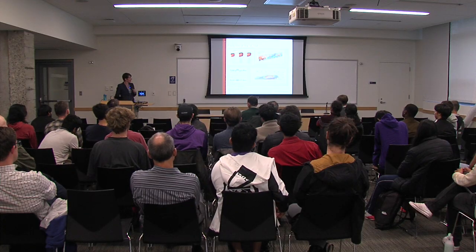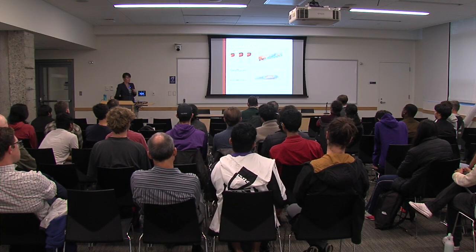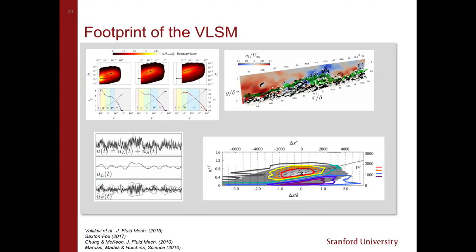So you would say that's a nonlinear effect. There are large scales here that are having an effect on the small scales. Good. You might even say close to the wall that if a large-scale positive excursion goes by a little eddy close to the wall, that feels like a higher Reynolds number, so it gets more energetic. That would be good, except for the fact that if I move away from the wall, this effect reverses. So instead of getting higher activity with a positive excursion, it actually suppresses far from the wall.